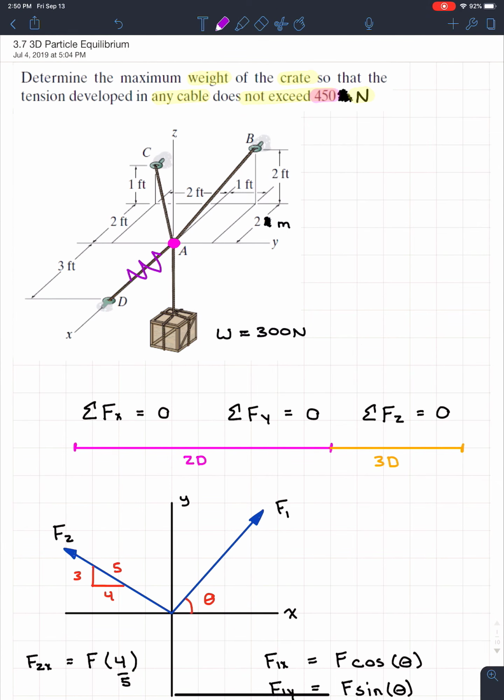Well, you'd solve for the three forces, and with that, you'd find FAD. And from there, you know that FAD is equal to the spring constant times the relative displacement. You'll have to be given the spring constant so you can find that relative stretch in the spring, something like that. And you guys know springs, we already covered it, so you should be good on springs.